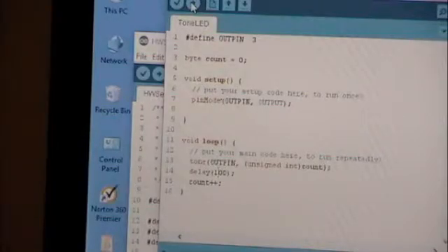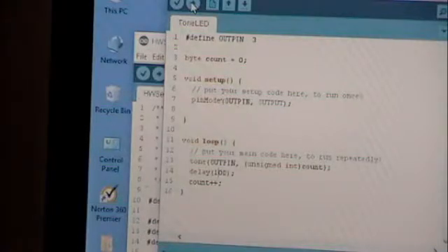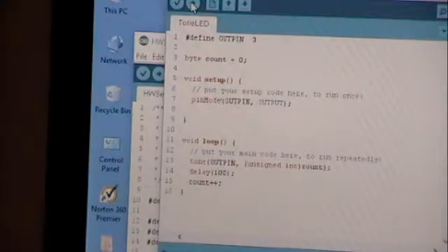When you look at your scope, and remember when we were doing the button clicks, and we saw some of them kind of went like that. That's an oddball frequency out there. It's impurity of your signal, and again, I'm lying by simplifying, but it has to do with phase delays. It has to do with different frequencies traveling at different speeds through your wire. It has to do with imperfections in the wire that cause reflections, where they actually bounce back at you and then get superpositioning. So, crazy crap.